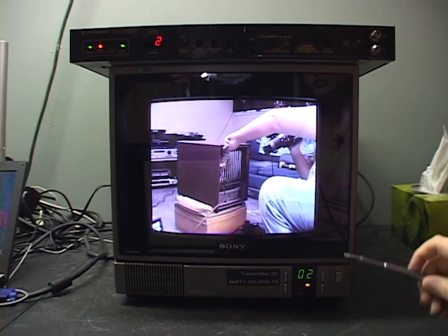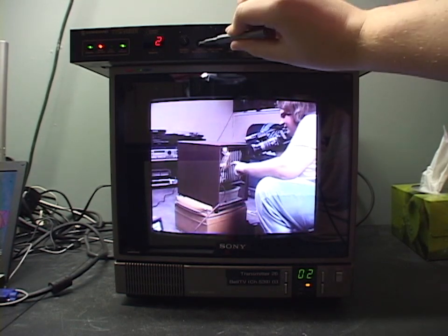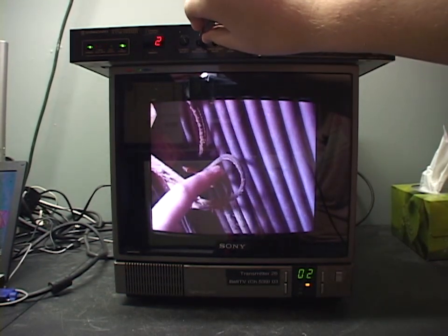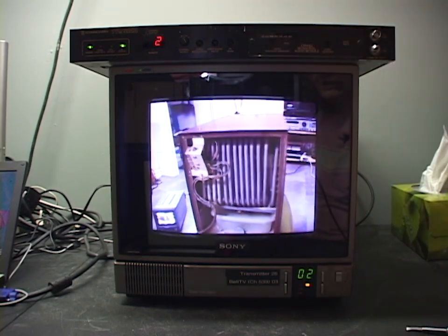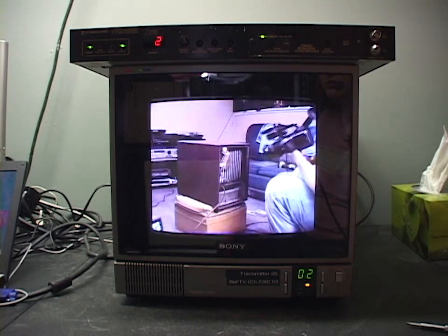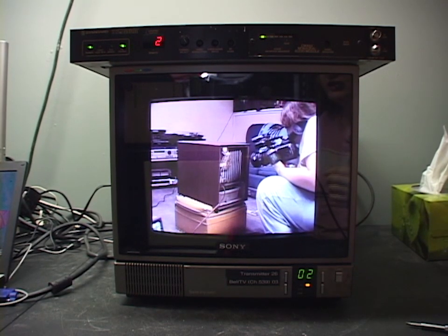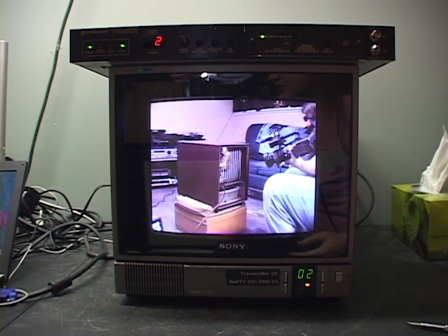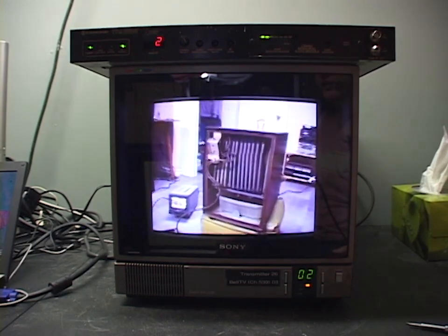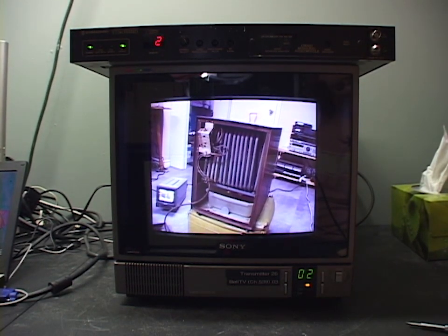You hear that buzzing. So if your video is overmodulated, you get that 60 hertz buzz. And I'm not certain on this, I haven't actually bothered to look it up, but what I'm guessing is happening is if your video is overmodulated, the video portion of the signal bleeds into the audio portion of the signal, and then you start hearing the 60 hertz refresh as part of the audio.